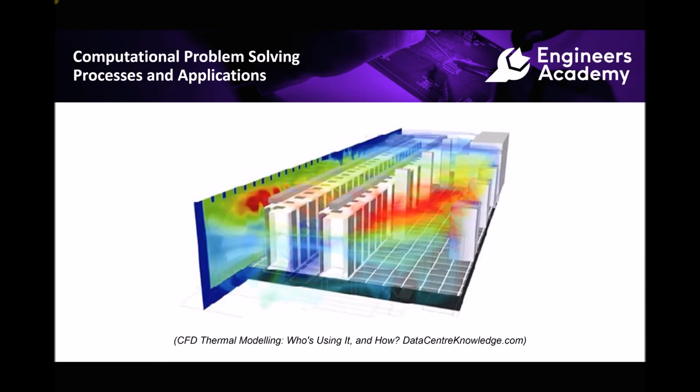And again, if we come to our complex thermal analysis, there's lots of things happening in this example because we've obviously got heat being generated by the servers, but we've got temperatures of our outside walls, we've got temperatures of the ambient air, there's going to be convection currents as a result of temperature variations. So we'd also need to know what's causing any circulation of this air. Now once again, if we don't define those boundary conditions accurately, then the issue we face is that we won't have confidence in the results that we generate. Now particularly with thermal problems, we have surface heat transfer coefficients, so between the server casing and the air, and we also have different types of convection, so we'd need to define that problem as accurately as possible.